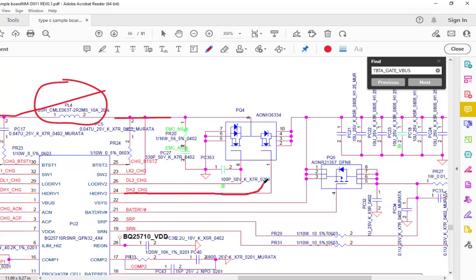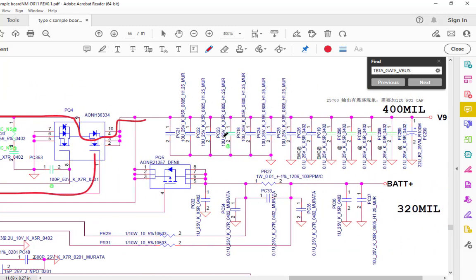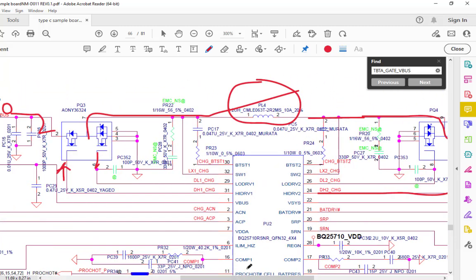What happens is this chip drives the upper gate, and then this voltage will pass from here to here. And these are the filter capacitors, they will filter all the voltage, and here you will get around 13 volt, and that 13 volt passes to the output. Okay, so in this way this circuit works, and it is controlled by these chips. This you have to remember.